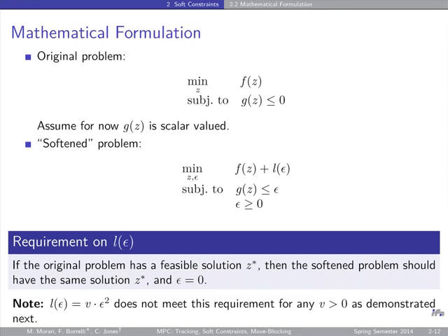So instead of the 1, 2, 3, 4, that's u, then you have 5, and here 6. Instead of 10 degrees of freedom, you have just 6 degrees of freedom. You simplify your optimization problem. And the nice thing for this type of strategy is that there are some rules on how to choose the move blocking such that the stability and feasibility conditions are preserved. So with move blocking, you can preserve the stability results. Not arbitrary move blocking, but somewhat restricted move blocking, and that is useful. If you want to simplify the optimization problem to solve, this is the way to do it. The other approach is not so great, because you don't know how to choose all those parameters, and all your theory is destroyed.